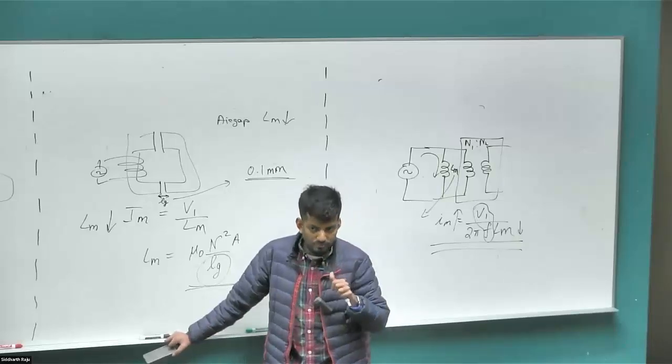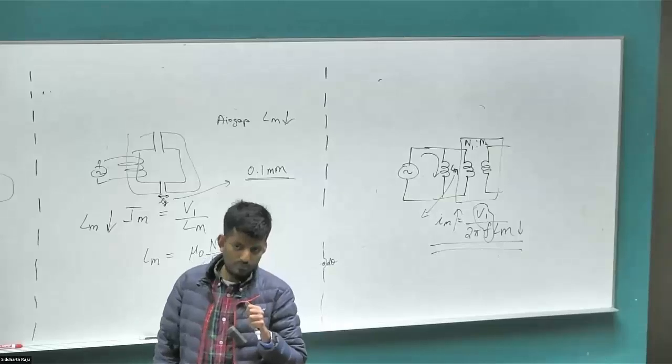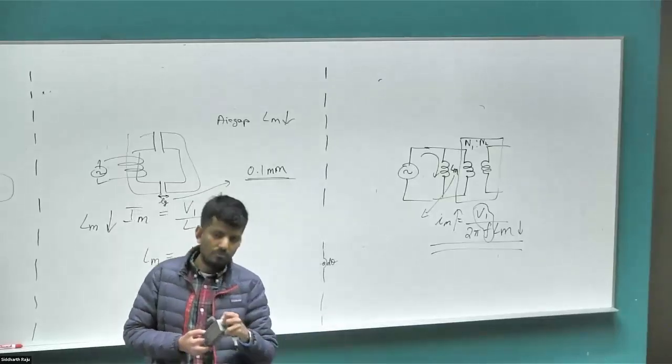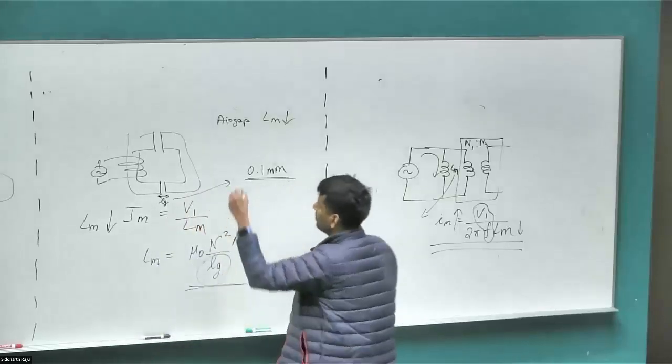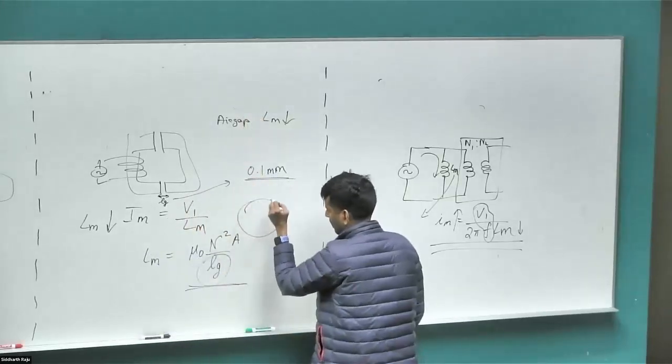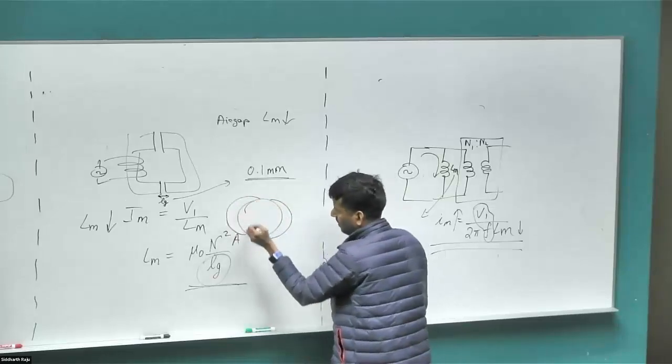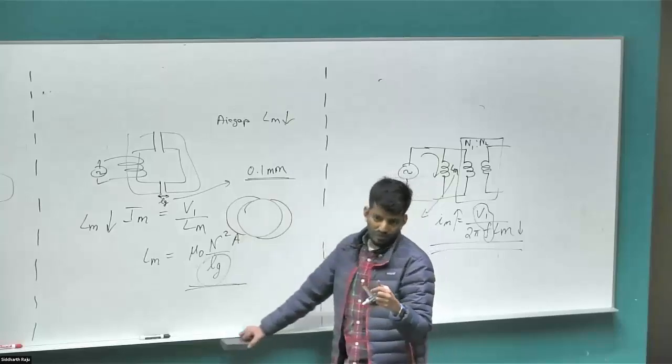Yep, John. Is it because in the permanent magnet motor, you had to carve part of the magnet out to make the sinusoidal field? Perfect. So we have two reasons. One, perfectly the answer John gave, where we have to carve this magnet, shape this magnet in such a way that the air gap length is varying. That is what was creating the sinusoidal field.